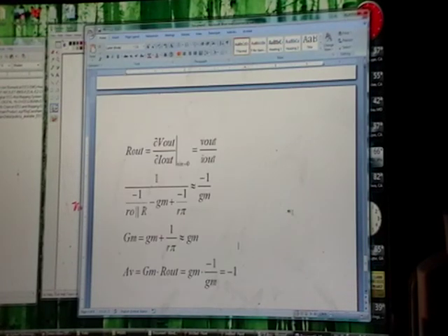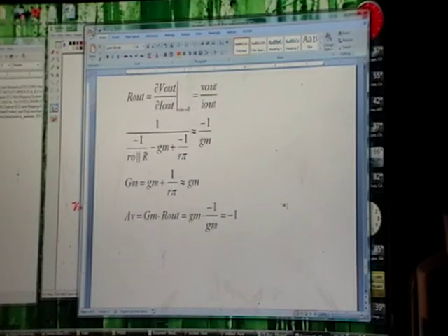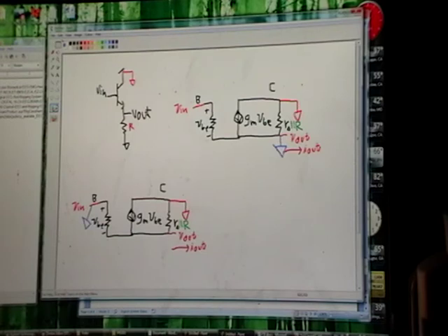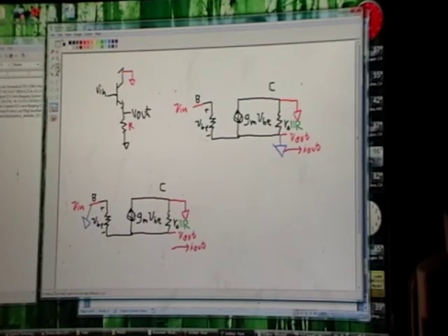Okay. The last thing that's important here is, now what we can do is we have this circuit here. We have our amplifier with a big R out, and it goes into this follower, which shows a low R out. That's great. That's exactly what we want.